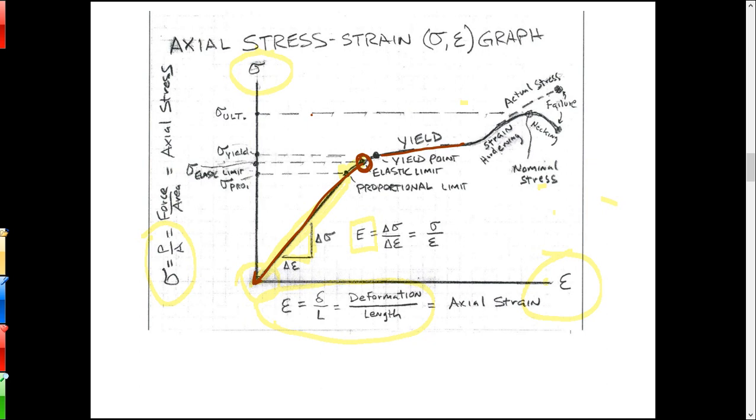Okay, now what's happening now is you've busted those bonds and everything's kind of given up and everything's stretching, and there's all these fracture lines in the atomic structure. It's actually a crystal. It's not a real clean crystal like a diamond or something, but metals make crystals. They have certain shapes that they bond into. Okay, and so you stretch that crystal out. Now you've got these fracture lines and they start moving around and they start running into each other. And then the material hardens up a second time.